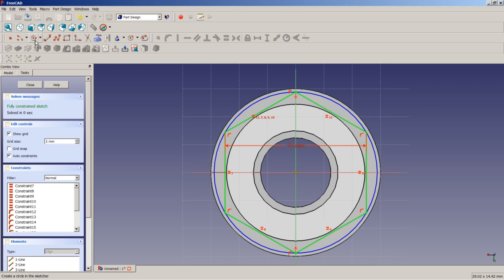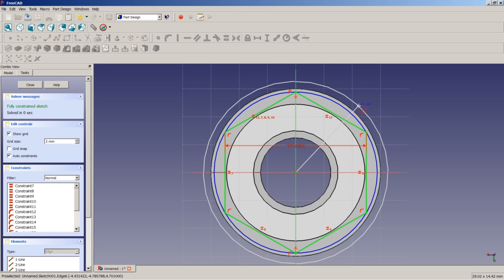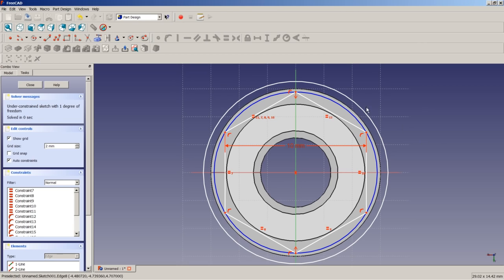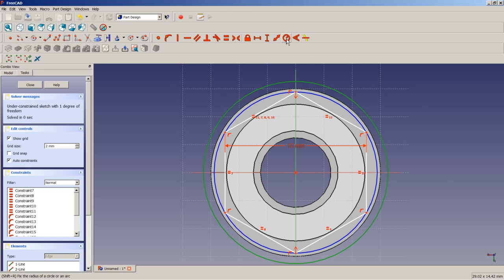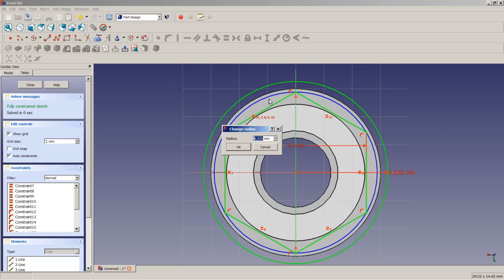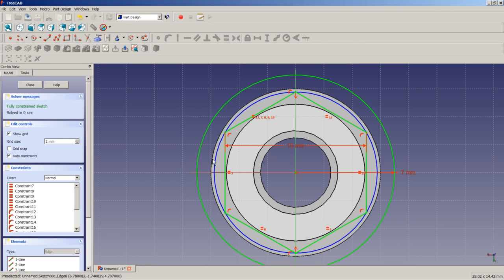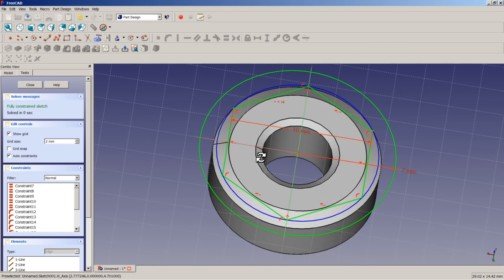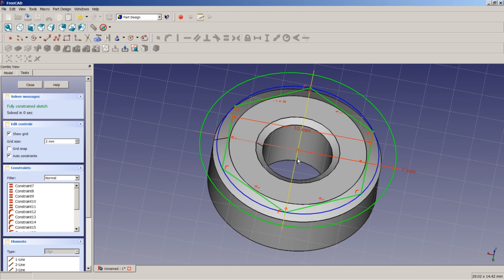We will then insert a circle from the origin here, and we will click once again here. And remember that we did a radius here of 6 millimeters, so we apply a radius to this circle of 6 millimeters or more. Let's say we use 7 millimeters in this case to get an overlapping for our Boolean cut, which is mostly a good idea.